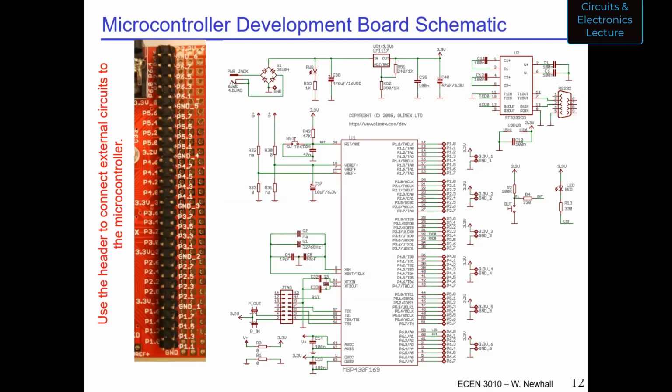This takes in DC or AC. Isn't that interesting? 4.5 volts AC or 6 volts DC. So there's something doing a conversion here. Microcontrollers operate off of DC. Look right here. This looks a whole lot like a full wave rectifier, and that's what it is. It will convert AC to DC, and here's a big capacitor that smooths out the rectified signal. This looks just like what we covered in class. And there happens to be a power LED right here to show the board is on.